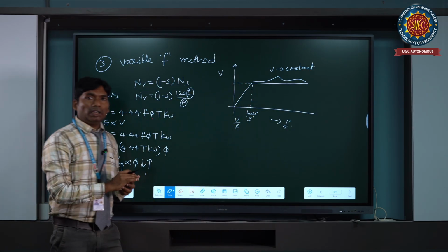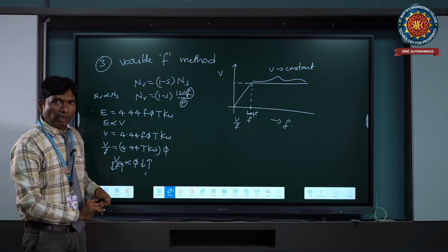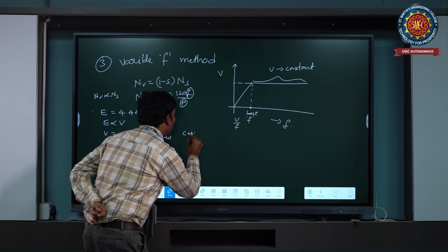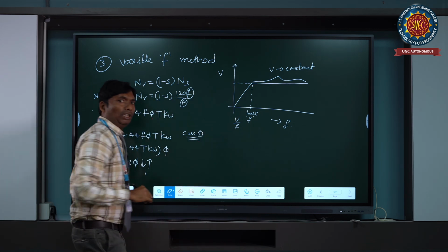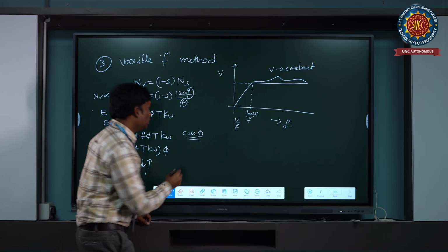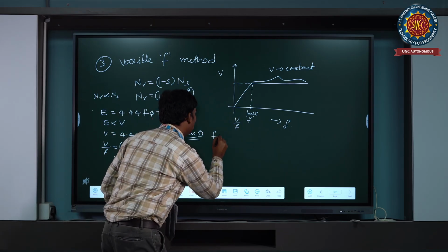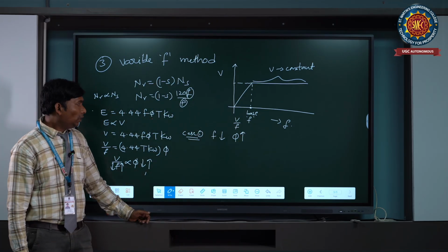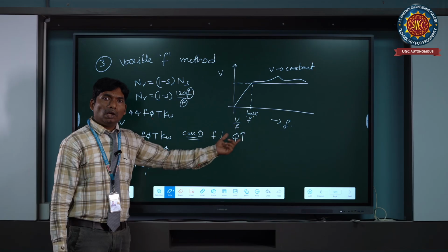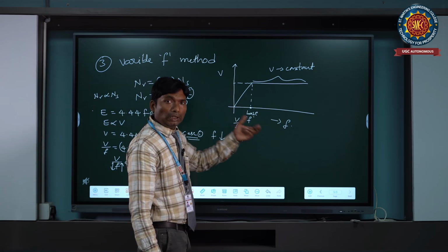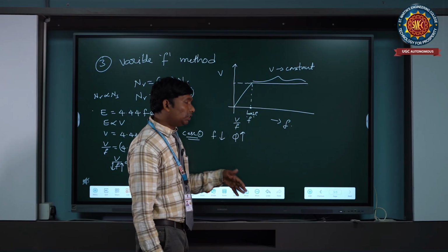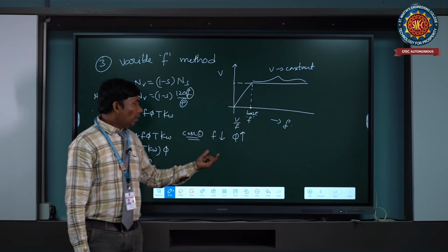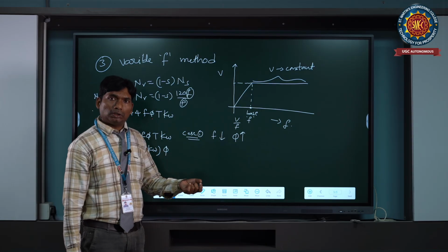In this way, we can control the speed of the induction motor by changing frequency. Here, we can observe the speed control in two cases. In case 1, as the frequency decreases, flux will be increased. When flux increases, the motor moves into the saturation mode. In saturation mode, very high currents will flow through the circuit.